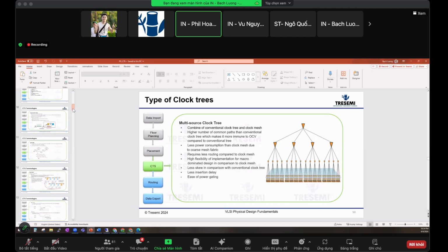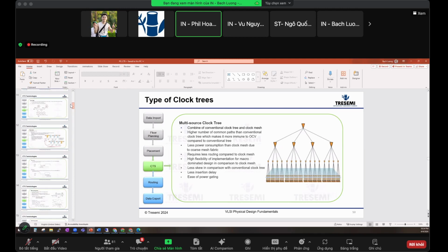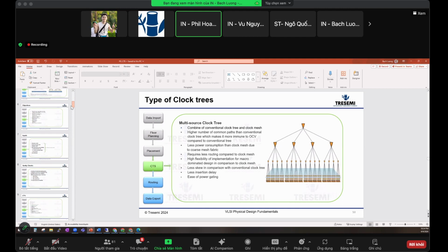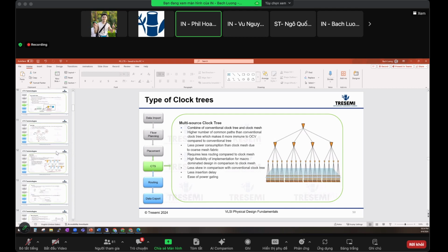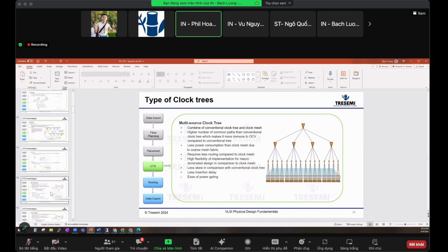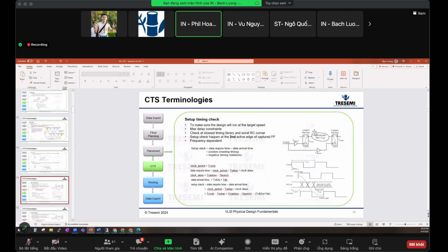When you simulate the worst case, assuming a certain distribution of your parameters, with 3 sigma on each of 3 parameters, you're simulating at 9 sigmas, right? So in a lot of cases, because of this and that, we're okay with having negative slack on the setup.